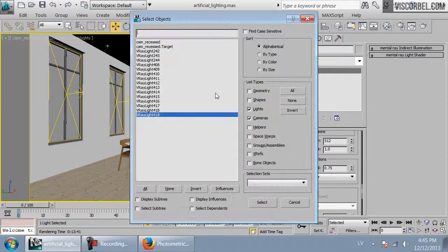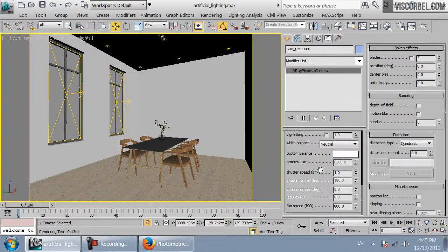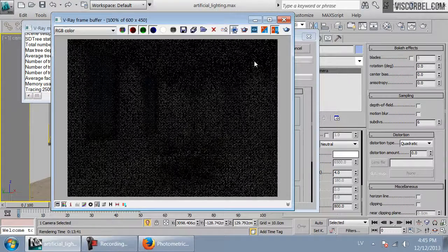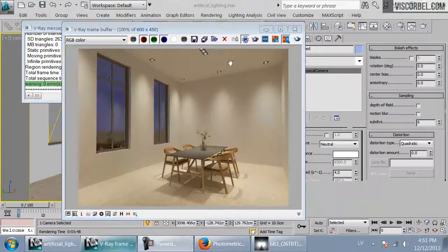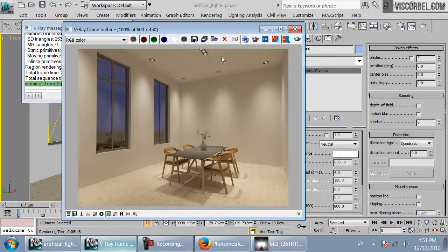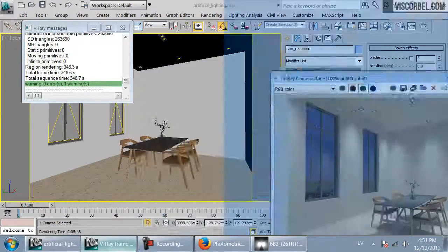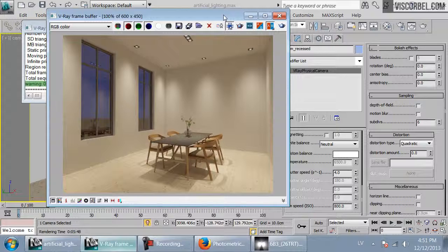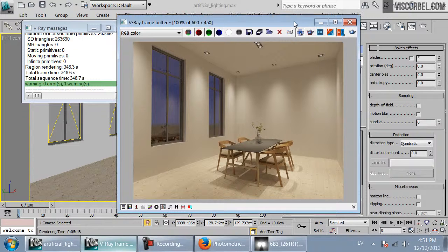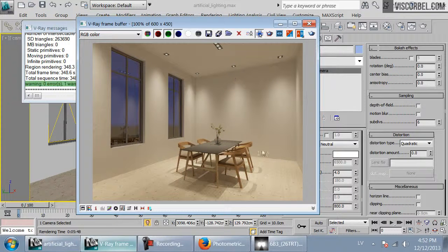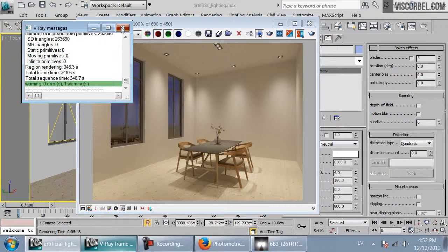Alright, and let's adjust the exposure for the camera to match the amount of light we have in our scene. So something like 1/4 of a second should work okay. As you can see, sometimes on these recessed lights you can get by with just simple V-ray plane lights with the directional parameter turned up, and you do not need any fancy photometric lights or anything like that. But sometimes there are cases where you want slightly more interesting patterns of light cast on the walls, and that's the case where you actually need to use those photometric files.